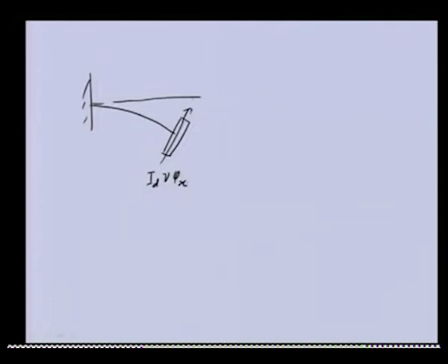If we again relook into the direction of the angular momentum, this particular disc is tilting about a diameter, let us say this is the axis. If we are looking from the top, the tilting direction is counterclockwise, and because of this the angular momentum is in the direction of this according to the right hand rule.